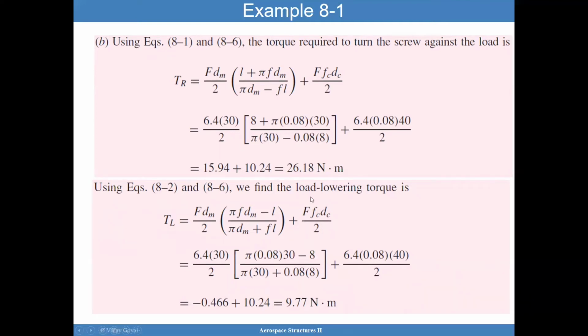And the main thing to focus here is that we can see here clearly that to lower the load, the torque required is less. And that makes total sense. You can see that working out. And to raise the load, the torque required is higher. So everything matches really well. You can see that it works really well.